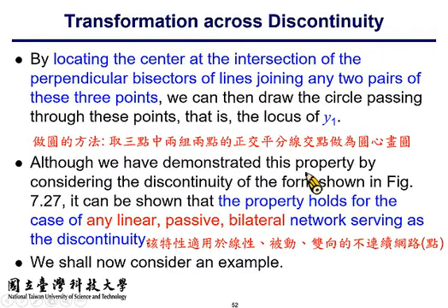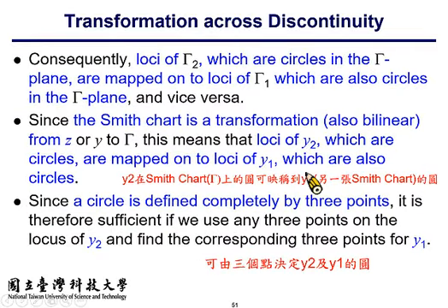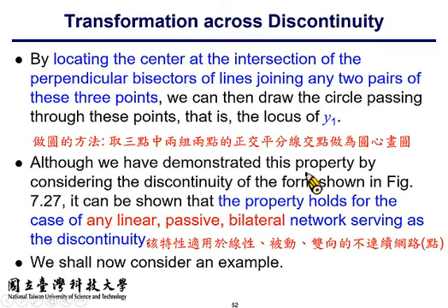All right, and so here are some descriptions about drawing the circle on the Smith chart, but I guess we will come back to this description later, after we get into the problem. All right, so because the transmission line itself is a so-called passive component, the bilinear transformation relationship, that is the one-to-one transformation relationship, is valid for any linear, passive, and bilateral.